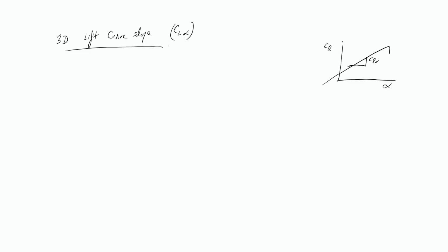So this is small cl alpha, that is nothing but the 2D slope. Alright, so this is applicable for an infinite wing, or a 2D flow. Okay. So let me also write the induced angle of attack expression, that we can write with pi AR or pi e AR as well.